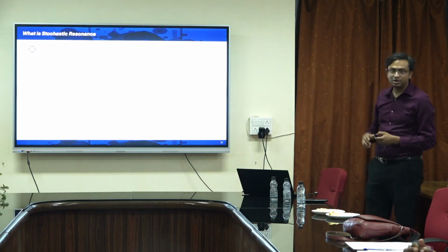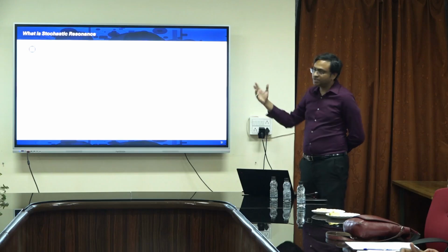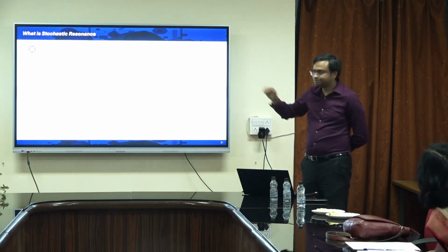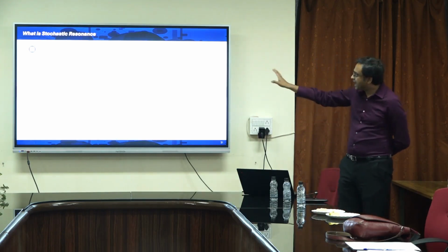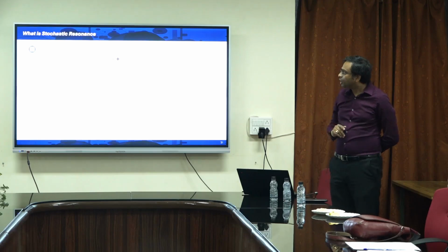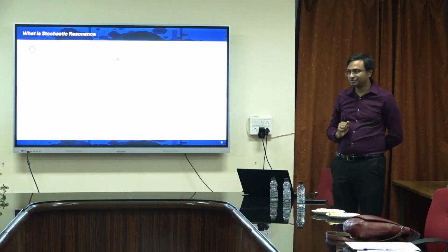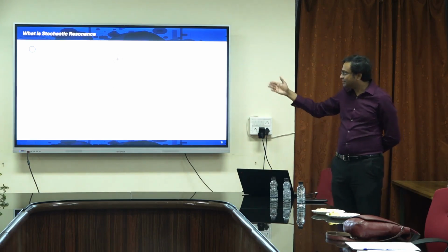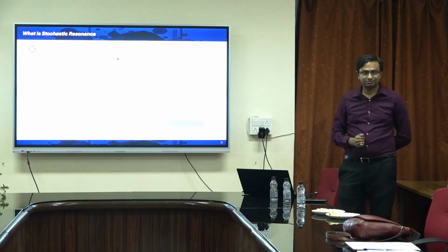So the concept is very simple. Let's say you have a periodic signal, and if the periodic signal is below the detection limit, you can never detect it. But now you add some white noise. When you add that white noise to the signal below the detection limit, occasionally the signal crosses the threshold of detection, and if you have a nonlinear, thresholding device, it can detect it.